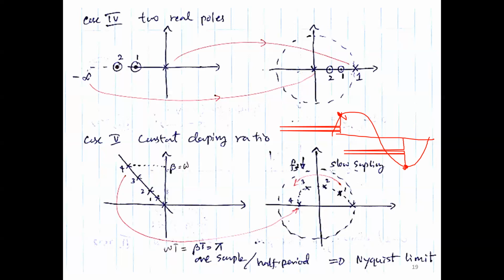Okay? There was no such thing in the original signal. You create it artificially, and we give it a name, alias. It's an alias. If you use that kind of signal to drive a controller, you are in serious trouble, and it will be very difficult to troubleshoot even.